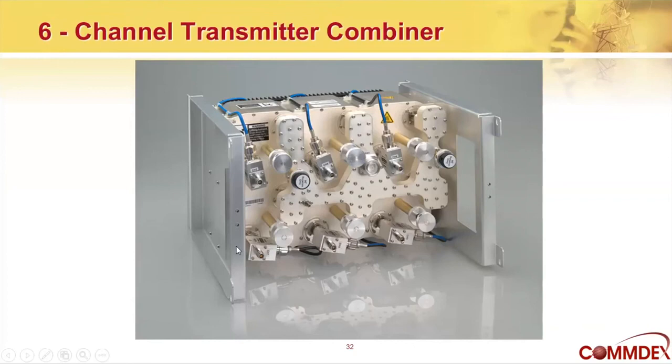Here is a picture of a 6-channel transmitter combiner, rackable, and it has all the pieces we saw in the previous diagram. Each one of those ports on there, there's 6 ports on there, each one connects to a transmitter, and there's a dual stage isolator on there, and you can see that the blue cables coming out are the port 3 of the isolators.